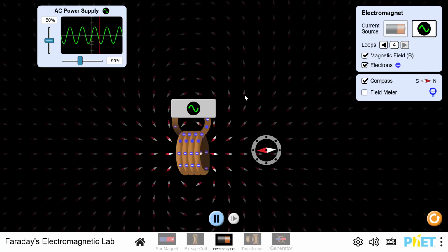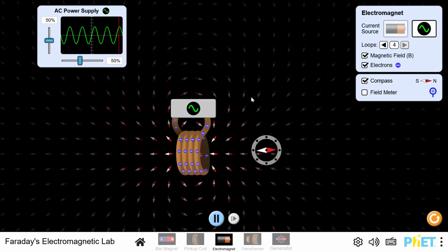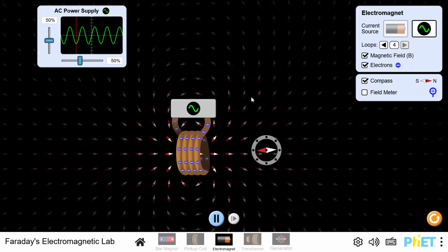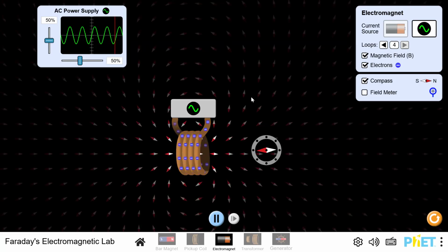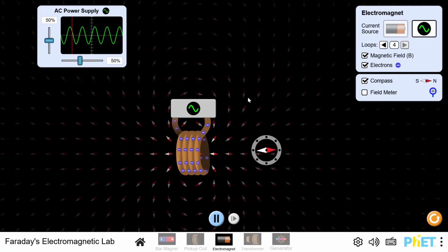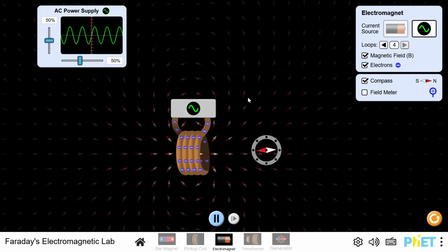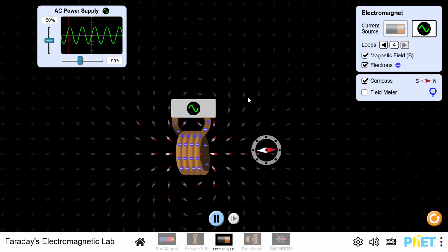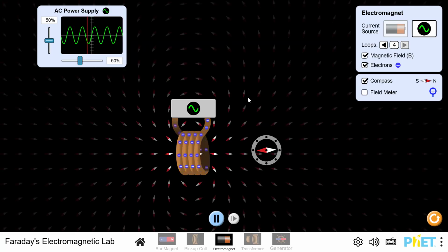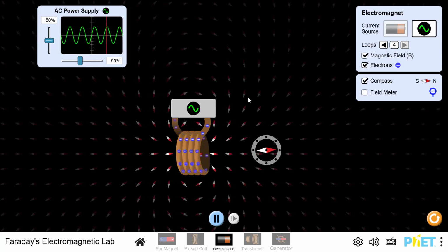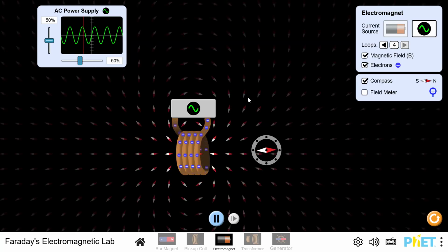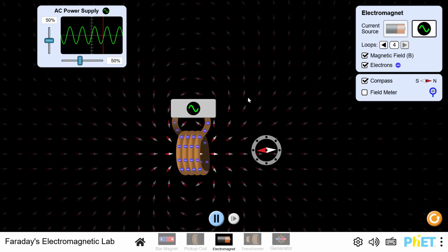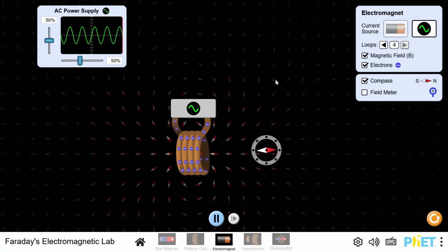Okay, so we have alternating currents, which I think I mentioned last week. It's a little more efficient to transmit long distances because you can get the same amount of power or wattage by using a very high voltage and very low current, whereas if you use direct current, the wires act as a sort of resistor if they're long enough, so you have a lot more loss.